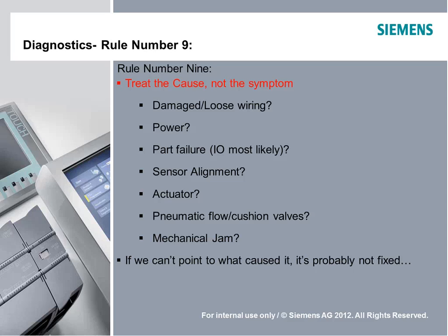We scratched our heads over that one for a while, and finally we figured out that the sensor was not seeing the pusher at the end every time; it was kind of passing by. So when it was fully extended, the sensor wasn't on. When it went by, it would flash, and most of the time that would work.